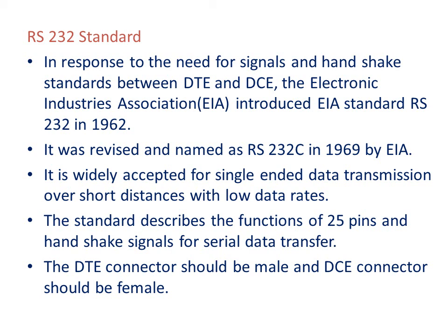RS-232C specifies 25 signal pins, and it specifies that the DTE connector should be male and the DCE connector should be female. So this is a very important thing here. The most commonly used connector is DCE, so it should be a female type.